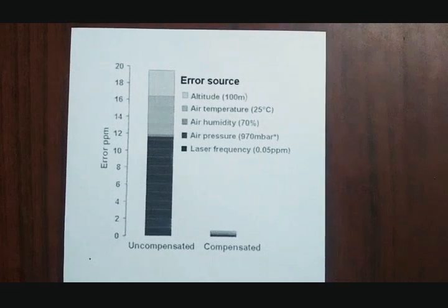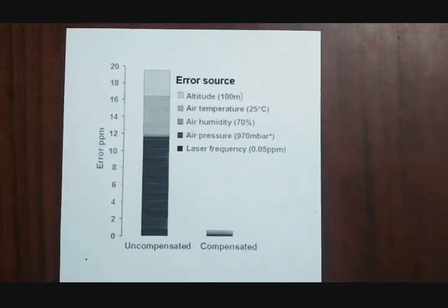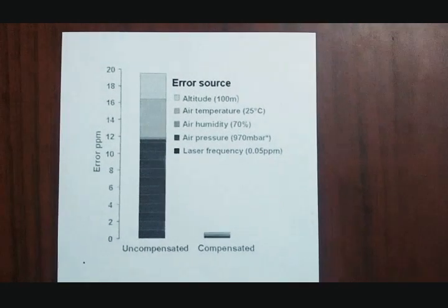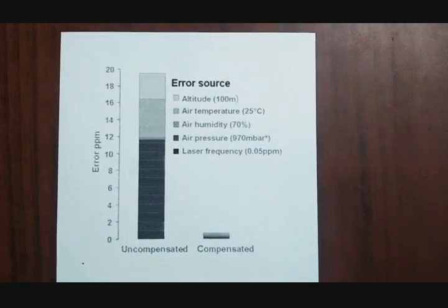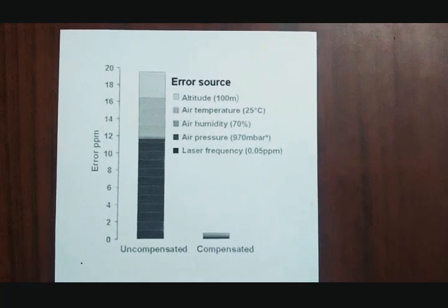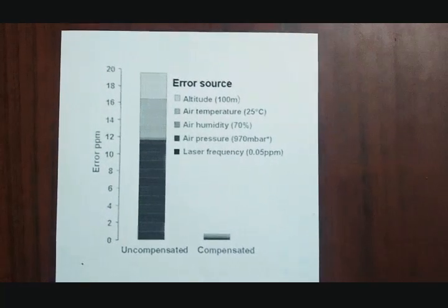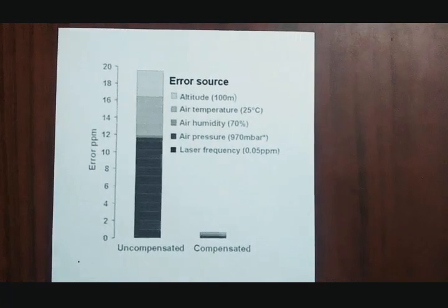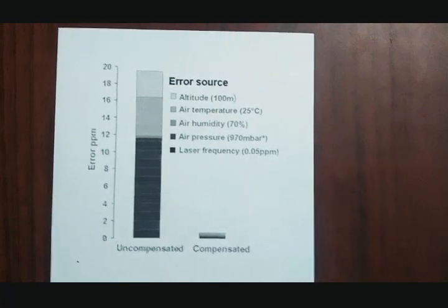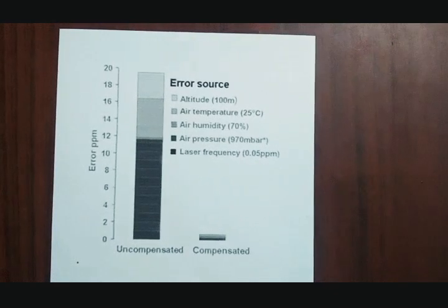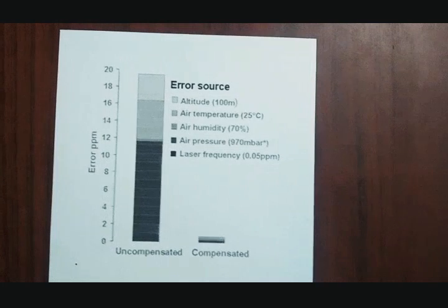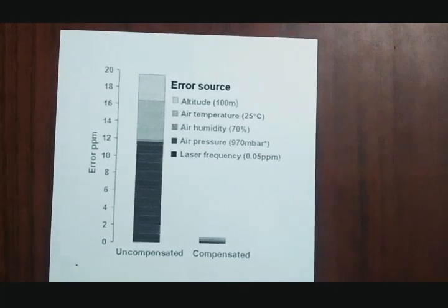So without reliable and accurate wavelength compensation, errors of 20 ppm to 30 ppm would be common in linear measurement readings when variations of temperature, humidity and pressure from nominal values are combined. These errors can be reduced by a compensation unit. The device measures the air temperature, pressure and humidity, then calculates the refractive index of air and hence the wavelength of the laser. The laser readout is then automatically adjusted to compensate for any variations in the laser's wavelength